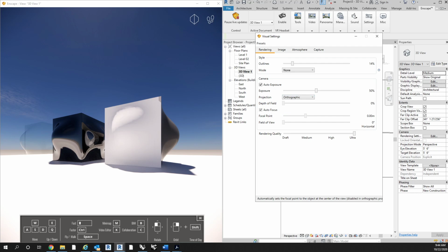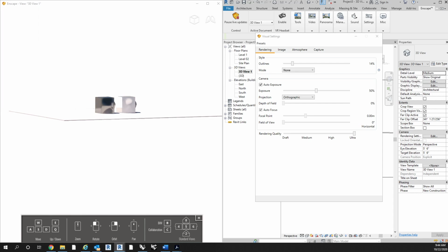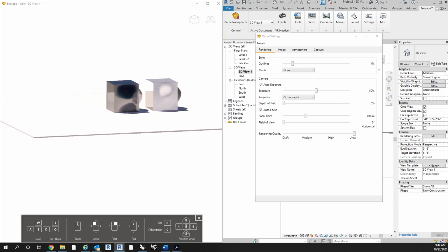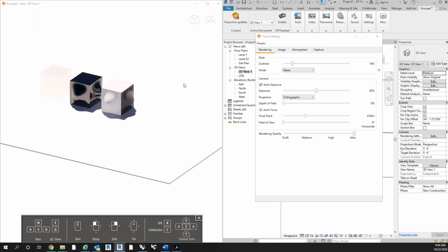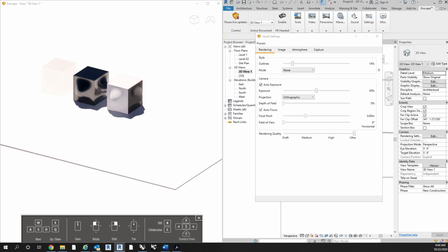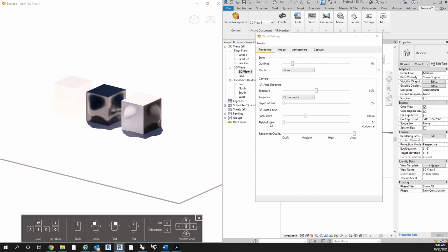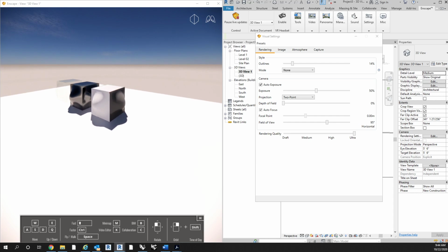And then you can also do orthographic, which is more of a true axonometric. This is a new part of Revit, Enscape. It's a little janky, a little hard to control, but if you do want to do a true axonometric rendering, you can do that. What I would suggest is you set up the axonometric in Revit the way you want it, and then open Enscape up with the orthographic projection turned on, and then take it from there, because it was originally set up for 2 point perspective and regular perspective.